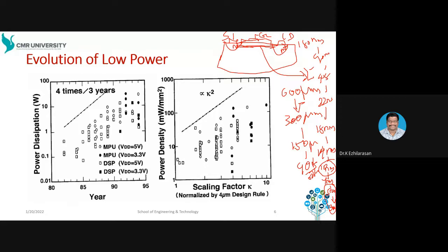But as you studied, the technology you used earlier is CMOS technology. But for these technologies, CMOS is not involved actually. CMOS was involved up to 45 nanometer only. After 45 nanometer, think about how the length of the channel will be. This is the length of the channel, and it keeps getting shrinking.